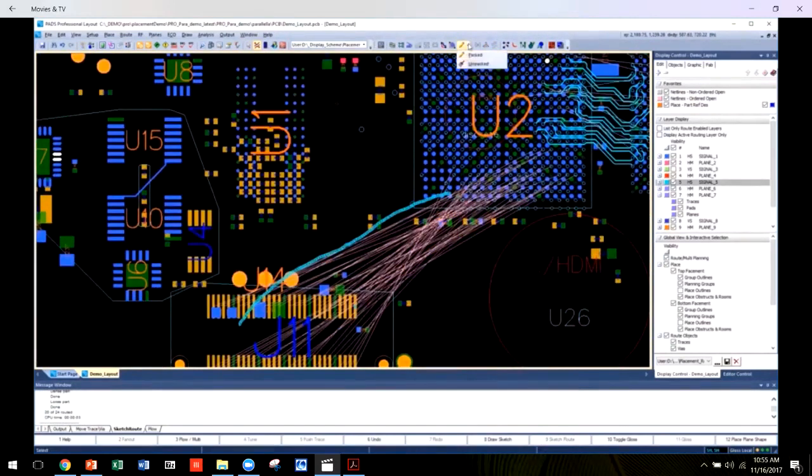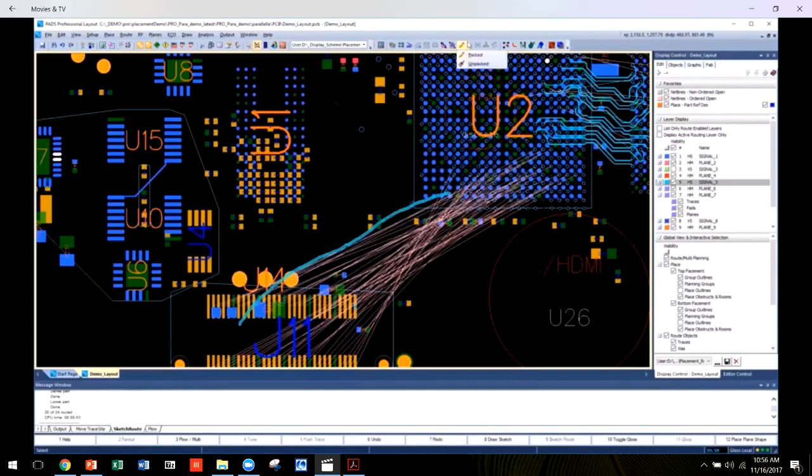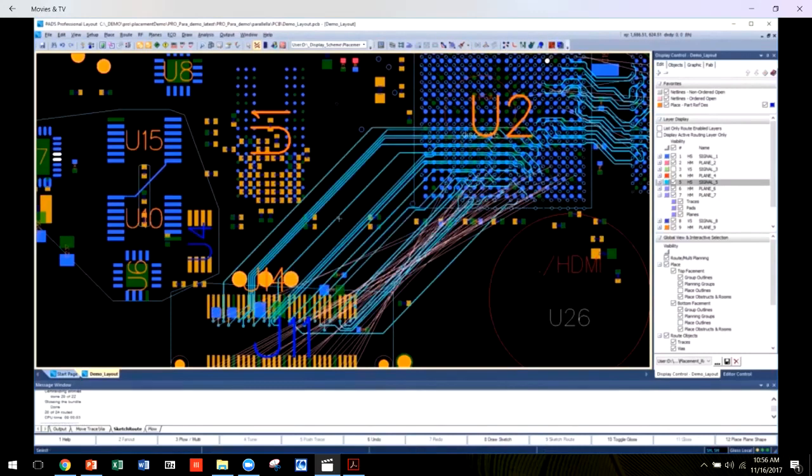You can sketch route in two styles, packed and unpacked. Packed packs the routes as closely as clearances are set, using gloss to minimize trace segments. You can add meandering by drawing a longer sketch path, as the algorithm will follow the sketch path more closely than unpacked. This is useful for tight bundles of nets when you want to minimize free space entering or exiting the highly dense BGA. You should consider using the unpacked style if you're seeing unnecessary trace packing or hourglass shapes.